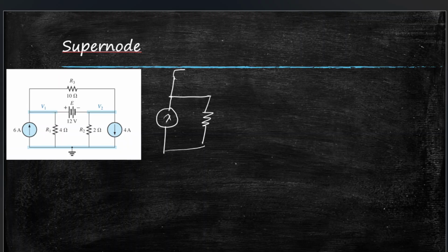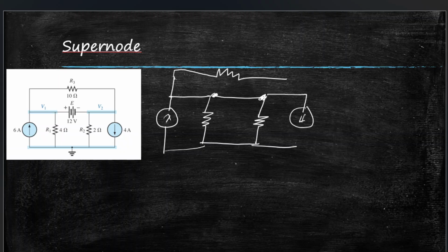Okay, we have another resistor up here, and then a short circuit. Now remember, when we remove voltage sources, we get a short circuit, and when we remove current sources, we get an open circuit. Okay, so here we removed a voltage source, so we have a short circuit. I have redrawn it with a short circuit. This is the short circuit.